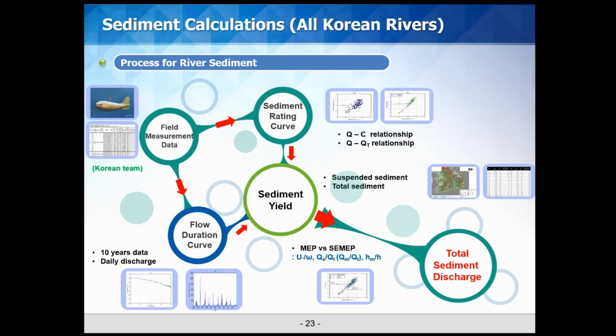So years ago, this is kind of a case study or an example here. We had a project in Korea with K-Water for about 3 years, maybe 5 years ago or so. And we got all the data from all the rivers they did in Korea. And it relates a bit to what we talked about this morning and how to estimate the sediment load in rivers. So essentially, you get your hydrographs all the time. You can get a flow duration curve. They measure mostly depth integration there. And then you get the sediment load from that.